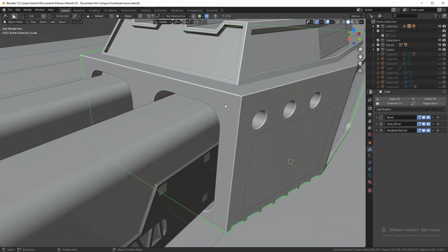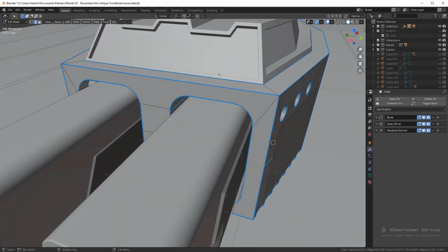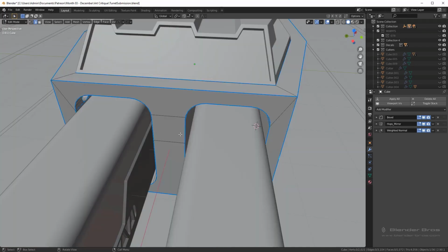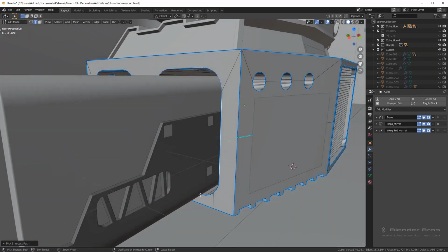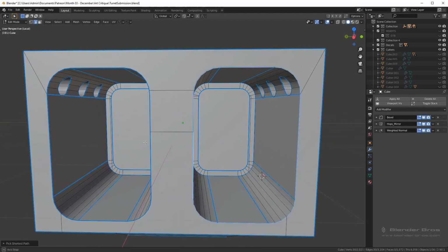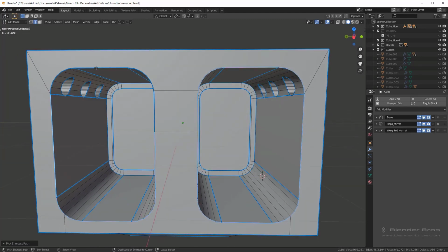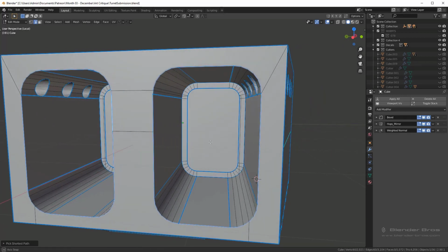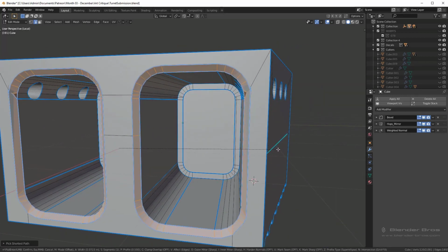If you wanted to be a little bit more technical and make the design pop a bit more, chamfers are super useful design elements. I use chamfers all the time now. I love them. A chamfer is basically a 45-degree bevel, a 1-segment bevel. So what we could do is come in here and chamfer these interior edges here. So I'm going to control click around, and to make this easier we could just press / on the numpad to get into local view. I'm going to go ahead and just continue around, and we're going to press Control B, run a chamfer.